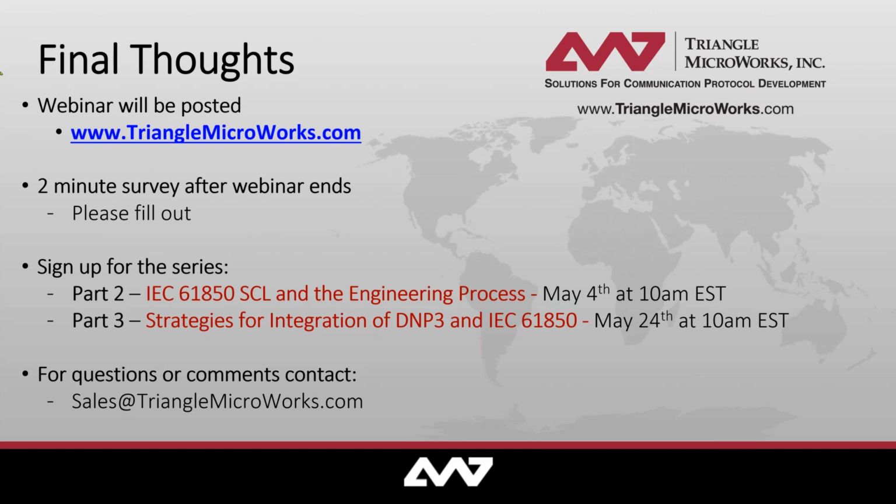As a short answer, master-slave is really coming from the time when we had serial links, where there was also a need to have media access control. So not just every device could start talking, but with an Ethernet network, we don't really need that. So that's why master-slave can be compared with client-server.